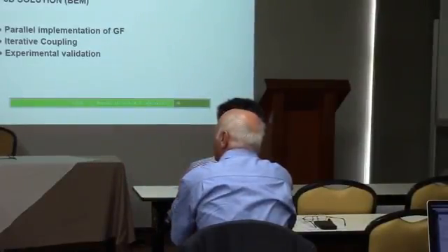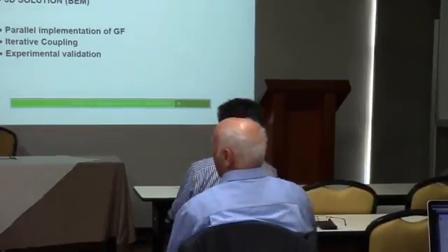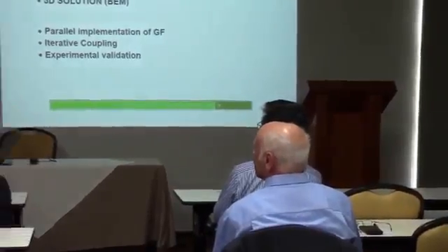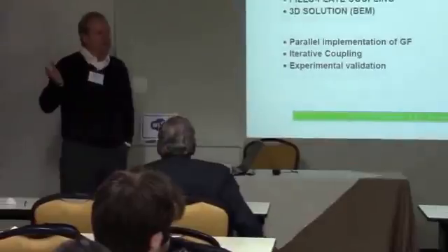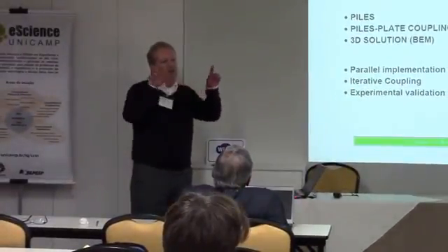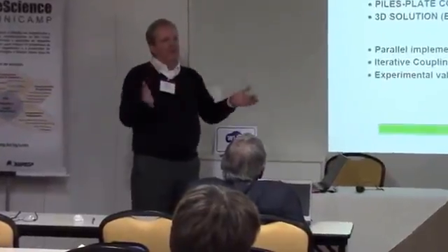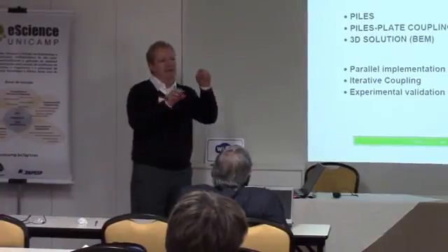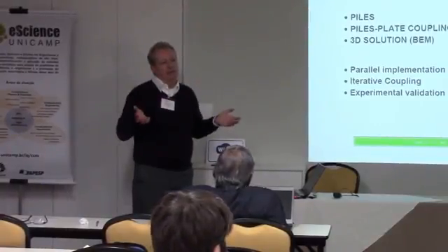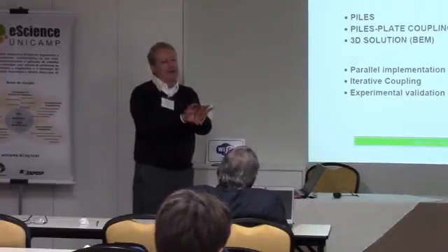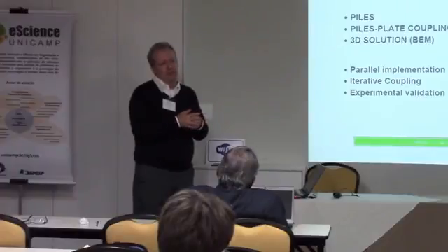This will have an influence on the reaction. There are two ways to incorporate that. One is very simple: you just add mass to the degree of freedom. Once it's rigid and you're doing it vertically, then you don't account for the effect of the embedment ratio or the fact that you have a built-in structure. But you can have an assessment of the influence of mass if you only do another equation. Other issues are much more complicated. If you have a massive structure, you want to embed it again. That's also possible. We've done this.